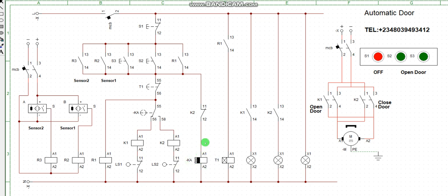When you energize this relay, it will put on the equipment and give you output. But how long will the output remain? It depends on the preset time. If you set it to 5 seconds, when the 5 seconds elapse, it will shut down. If you also want to use this relay as an off-delay timer, the shaded place here is the off-delay function, and this other side with the cross portion is the on-delay function.